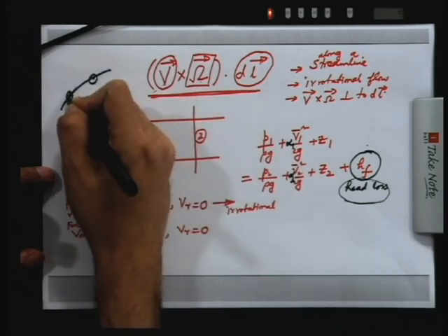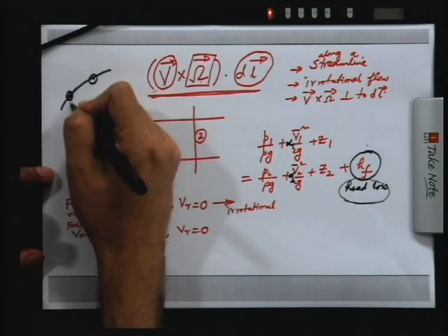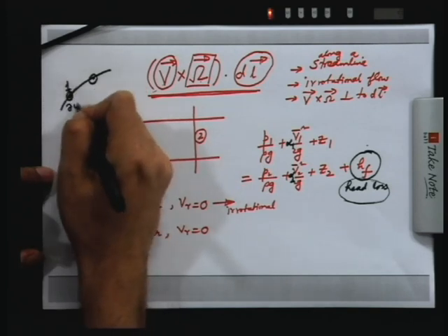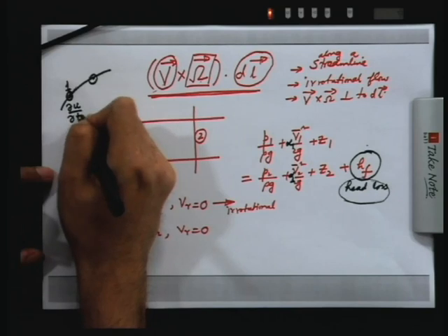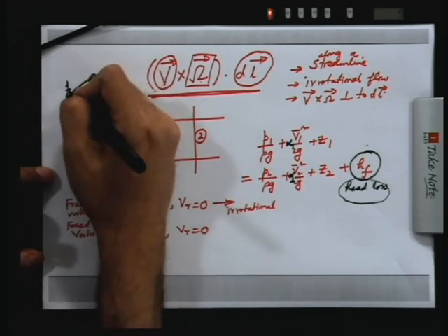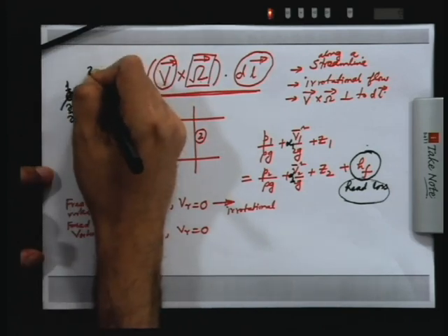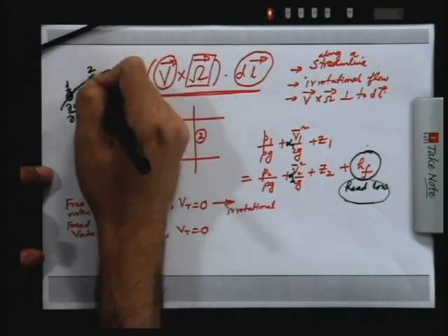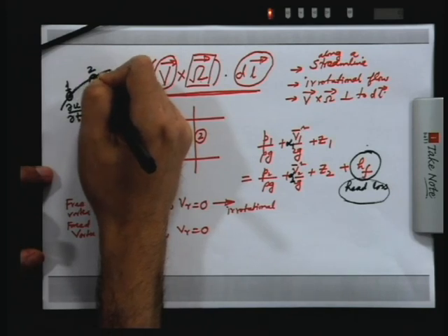At the same point 1, if the fluid particle had remained, then because of change in velocity at point 1, there would have been a del u del t. So, at a given location there could be a change in u due to change in time. But by the time the particle has come to a new location 2, it finds a new velocity, because it has come to a new location where the velocity field is different.